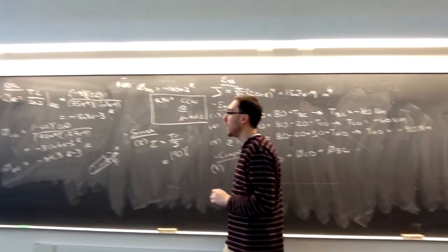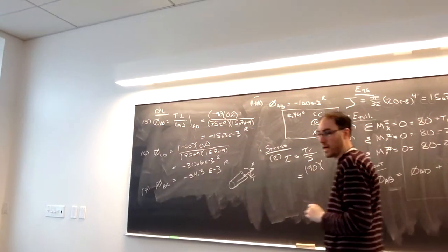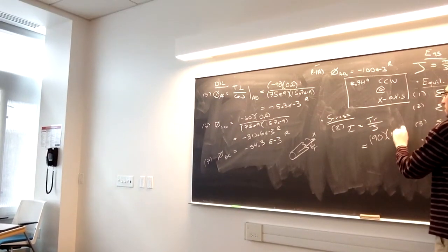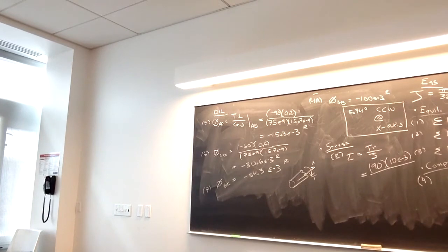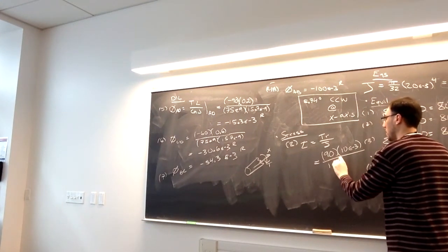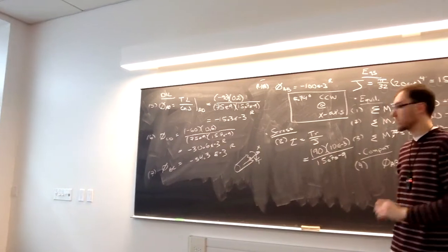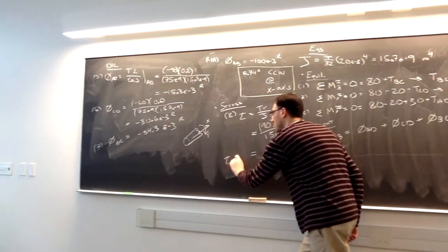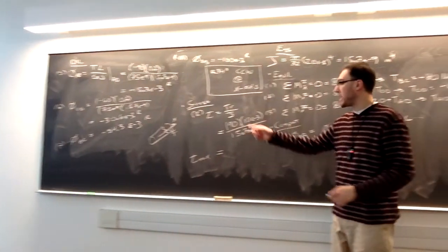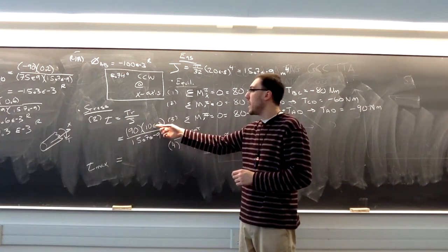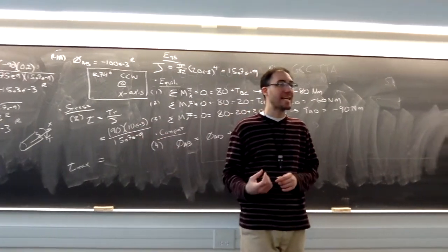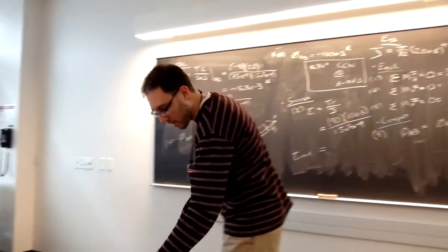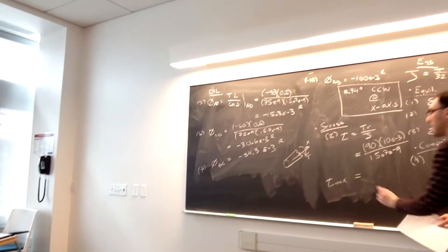We have 90 Newton meters times the radius, which was 10 millimeters, divided by the J, which we calculated earlier. So the maximum shear stress, again, is at the outside radius, so I'm only calculating it there. And I'm only calculating it in section AD, since that had the highest internal torsion. The maximum shear stress for this is going to be 57.3 megapascals.